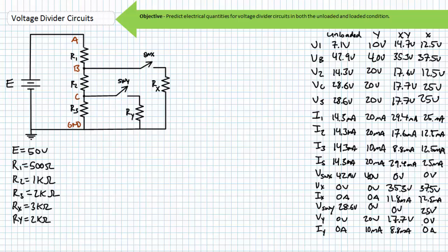Each different combination of switch positions presented us with different current paths and resultant voltage drops. Every situation was different and necessitated a completely new analysis because they were completely different circuits. Notice at no time did I ever have to resort to reducing this circuit to a single total resistance and return through a tangled mess of simplifications to solve for the desired quantities. At all times I used basic series and basic parallel properties and repeatedly made use of Kirchhoff's voltage law and Kirchhoff's current law to quickly and directly solve for the desired quantities without any back-breaking labor.